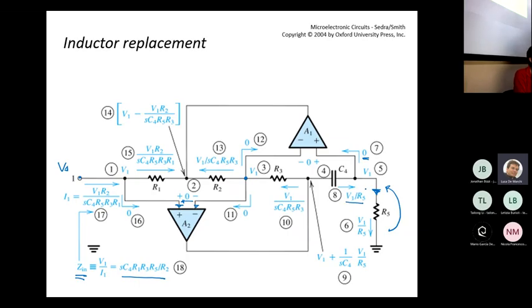If you know the current which flows in an impedance, such as the one realized by C4, you can compute the voltage drop across the impedance by reapplying the Ohm law. So you can compute the voltage potential that you have at this node, which will be V1 plus the voltage drop across the impedance associated to this capacitance.